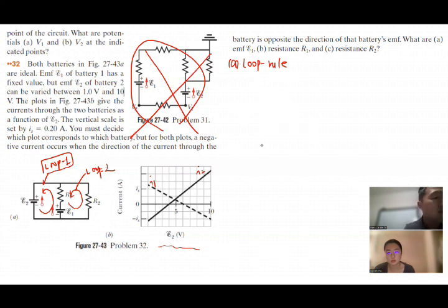Why not just set up the direction of the loop the same as the current flow? If you just focus on loop 1, then this battery creates the current flow clockwise, so you can think of that as I1. For the sake of clarification, you can set up loop 1 in the same direction as I1.